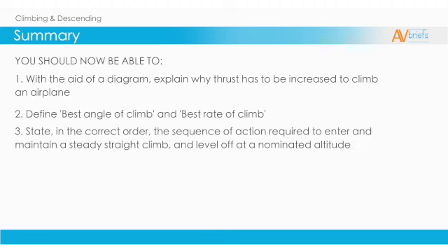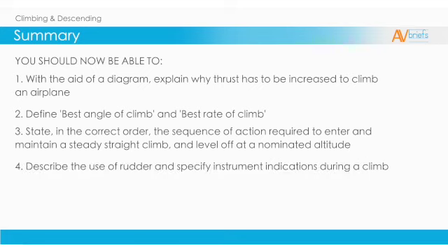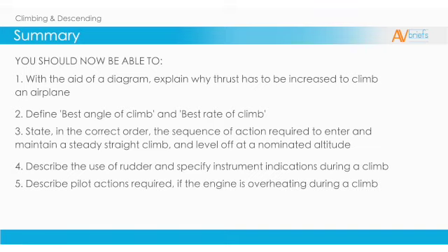State, in the correct order, the sequence of actions required to enter and maintain a steady straight climb, and level off at a nominated altitude. Describe the use of rudder and specify instrument indications during a climb. Describe pilot actions required if the engine is overheating during a climb.